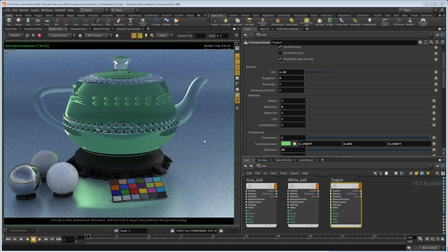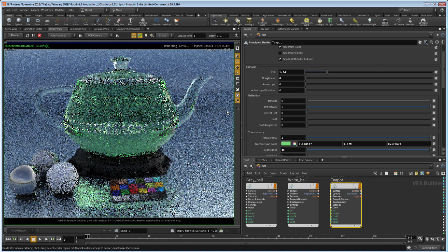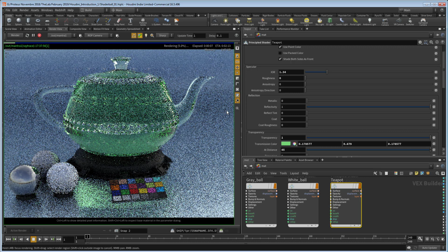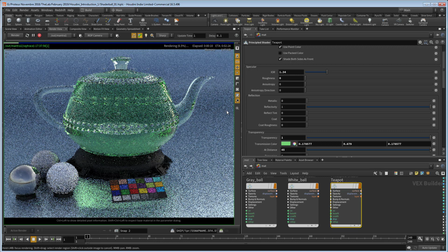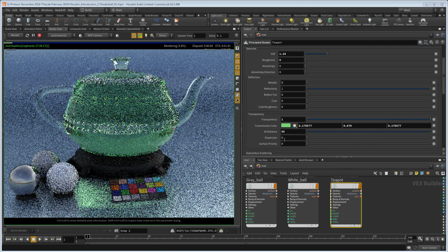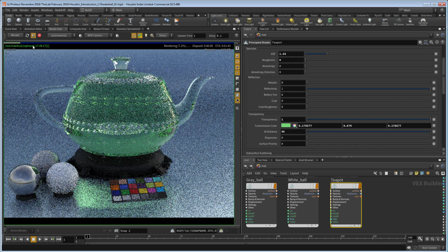And obviously we can have back our reflectivity because actually it was 0. So you see we can have back the reflection, so we have reflection and refraction. And we can, for example, work to have also the dispersion. You can play with the dispersion value there. By the way, if you like, you can, for example, pause the rendering, and when you like, you can restart it.